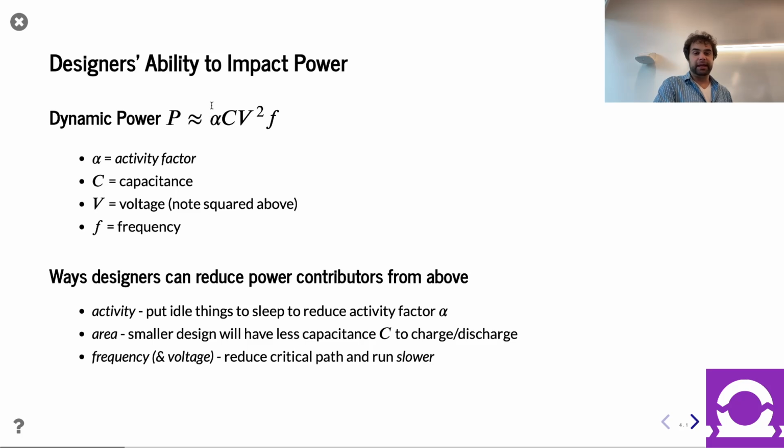There's the activity factor, which is how often something is switching. Interestingly, if you want to think of the typical activity factor, it's actually really low. I have a bias toward this, as I have research that takes advantage of that. It's a few percent on the average digital circuit. A few percent of circuits are switching, and a lot of circuits are not changing.